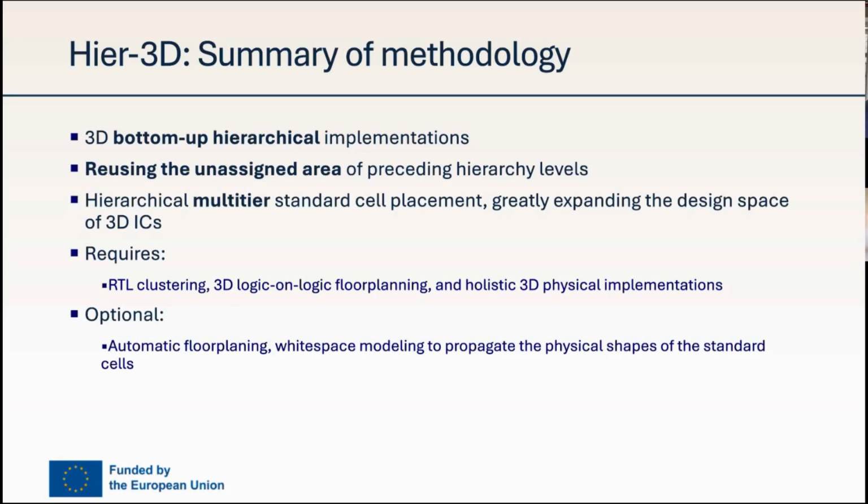If we want to implement completely the rough idea that I described right now, you see that some of the elements that we need are first an RTL clustering approach in such a way that we can cut our design in different steps. We want a logic-on-logic floor planning approach that we have to do at the very beginning. And also, we require a holistic approach for the 3D physical implementation that we are implementing using Macro-3D.